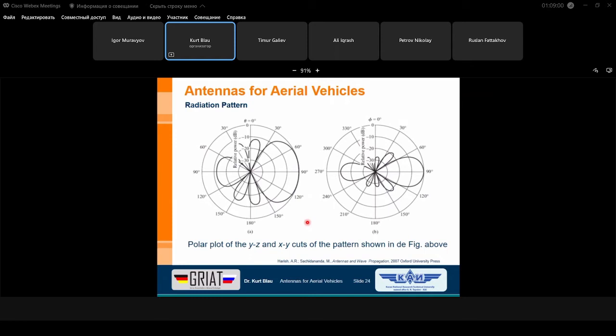Directivity means it's the pattern of the antenna related to a certain reference value, in most cases the highest gain value, so that from the diagram or the radiation pattern itself, you cannot determine the gain value of an antenna. What does it mean? I will explain it with the next slides.